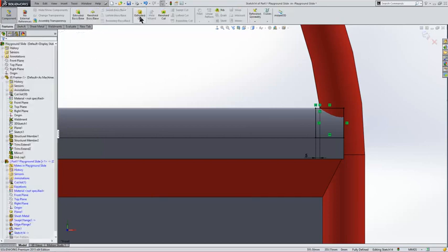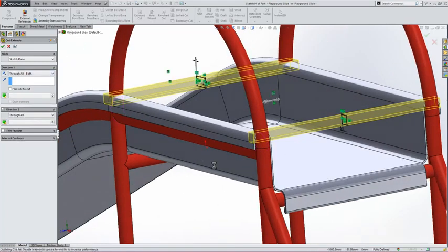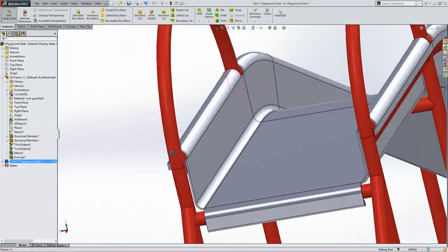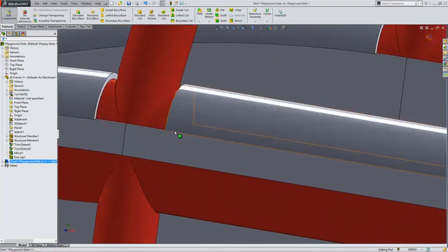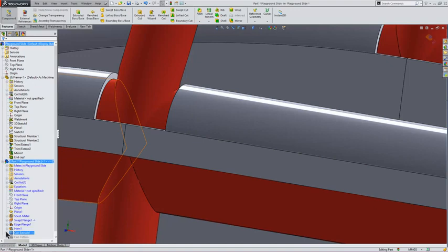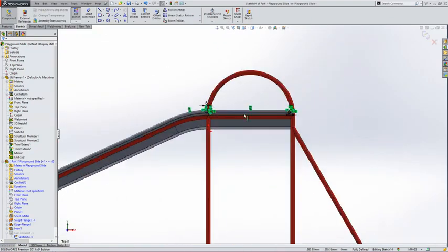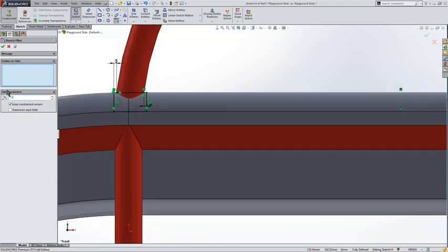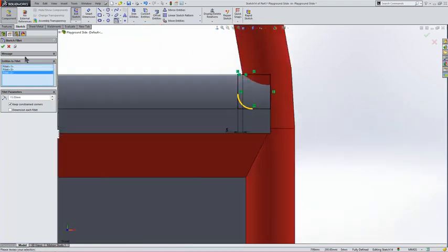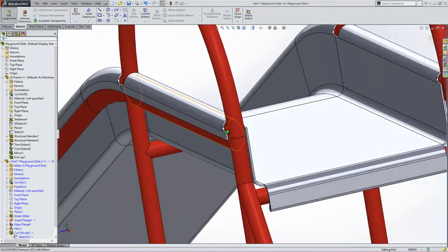So we'll take that sketch and we're going to cut. We're going to cut right through both. Okay, give that a green tick. What that has done, it's taken away a nice cut, which is giving us our, looks like we've lost a little bit on our sketch. Looks like we lost the rads there, so I'll just add those back in. 20mm, let's do 20mm, 15mm, that's probably a better size. Okay, we'll do one on this end as well, green tick. Alright, so that's cutting out a really nice shape for us there.